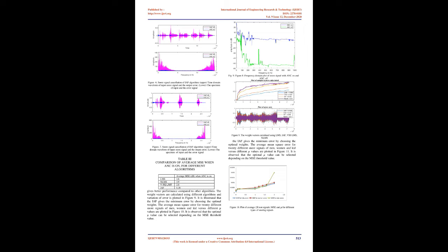The signal from the microphone J can be shown as given, where x_j(n) is the jth reference signal of length L. The secondary microphones have K channels, where D is the threshold value. The samples below this value can be neglected, which reduces the computational complexity. This can be adjusted according to the variance of input signal. The interval weights are updated by using the equation; updated weight coefficients are calculated using equation 9. In this algorithm with the interval step size the optimal weights of the system are identified which reduces the MSE.